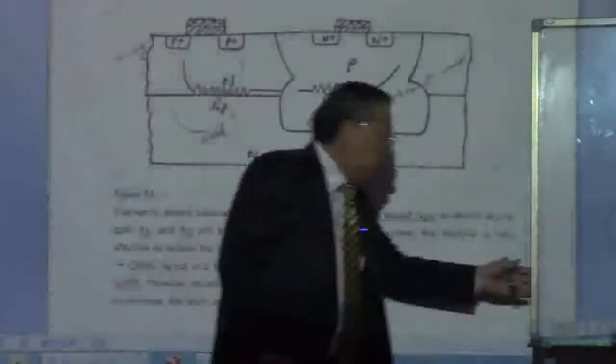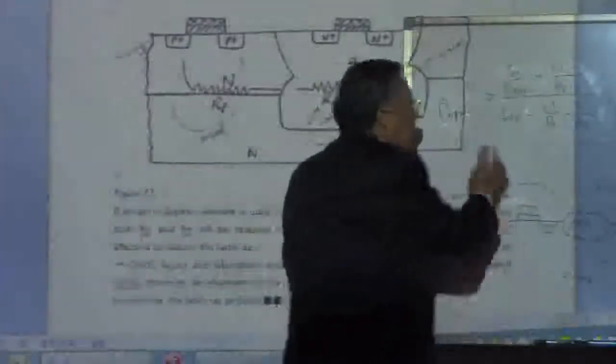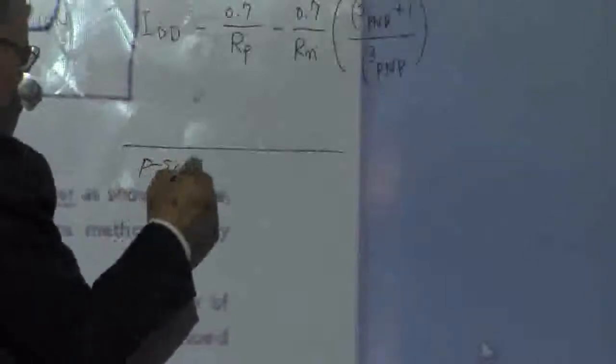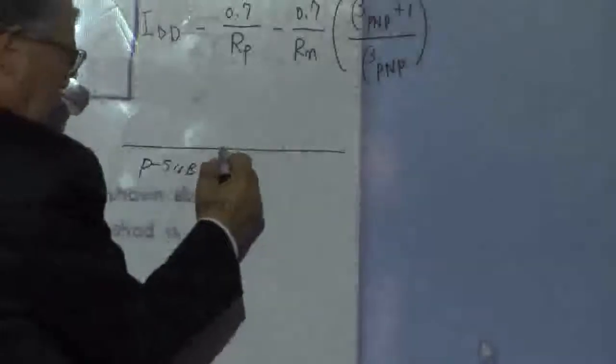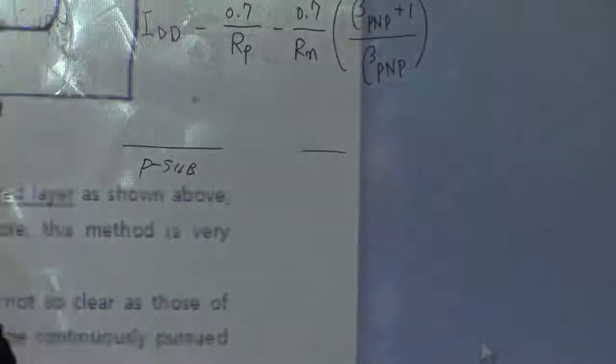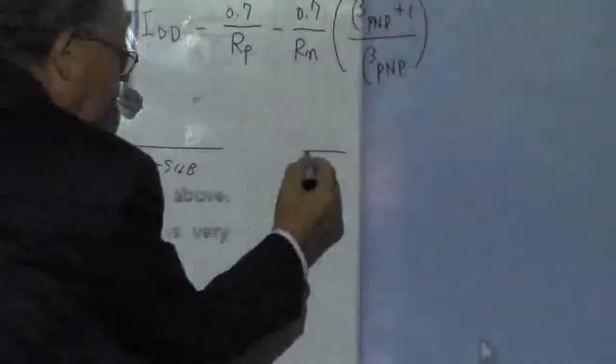You know, in bipolar transistors, this idea comes from bipolar transistor making. In bipolar transistors, what you do is you have, say, a P-type substrate, okay, and then you implant the N plus layer and then do the epitaxy.